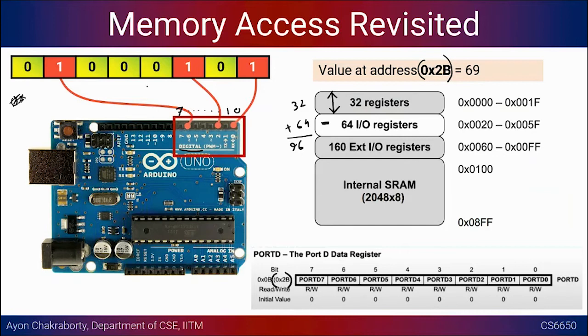So this actually sets bit 0. So the 0th pin, if you attach, let's say, an LED to pin number 0, this should turn on, given that we want to use all of these pins as a data output, right? As we have seen, pin mode for pin number 0 has to be output, and the same holds true for the other ones.